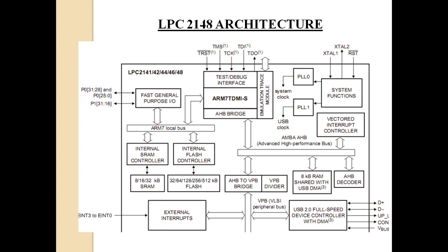So how will you take this light to the actual data present inside the chip? For taking the light, if you see an EPROM IC, in the center there will be a transparent window. Through that transparent window, ultraviolet rays will be taken to the actual silicon chip sitting inside the EPROM.